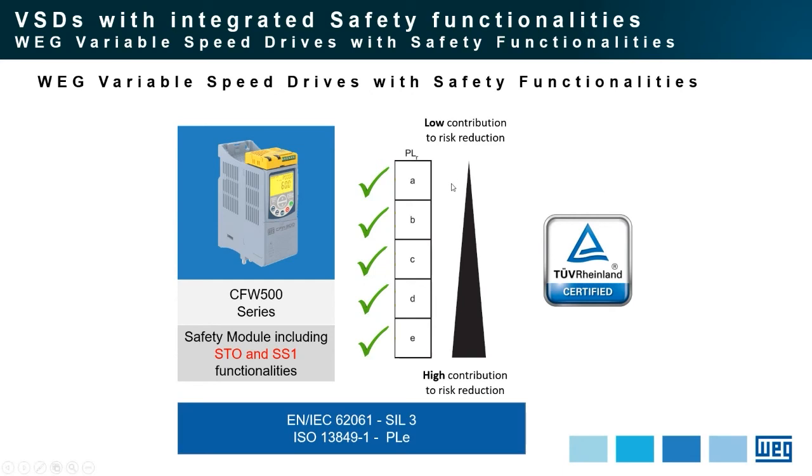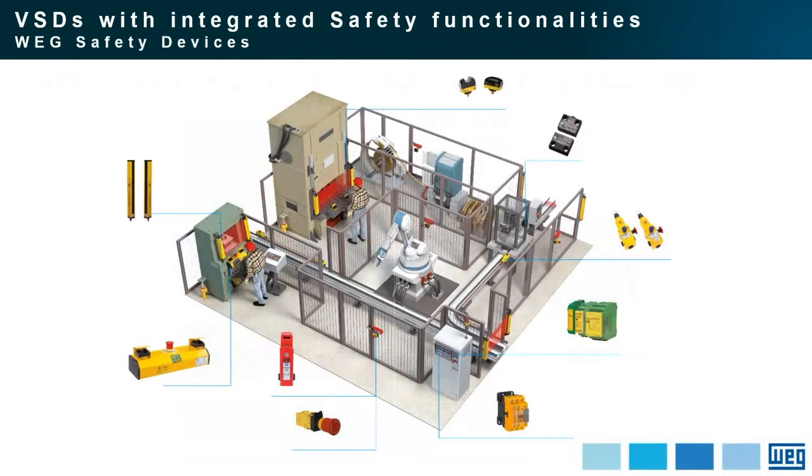So it is possible to use the CFW500 with this safety module, this yellow module installed here on the top of the drive, in applications with low contribution to risk reduction, up to the higher contribution to risk reduction. Remembering that all of them, the CFW700, CFW11, and also the CFW500, are according to the TÜV recommendations and are TÜV certified.